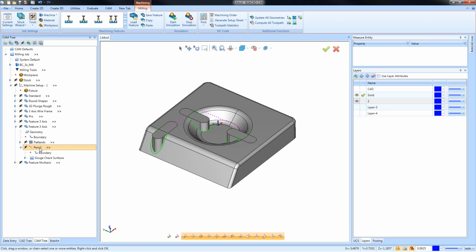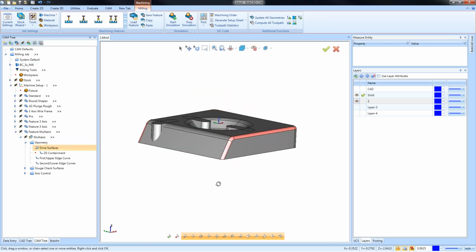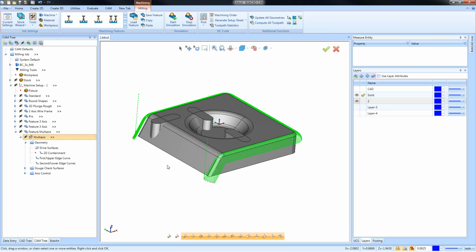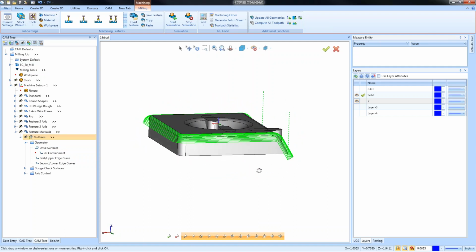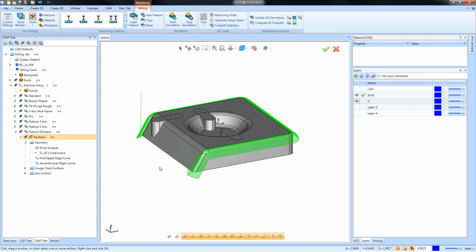And then as you elevate, if you become a Mill Premium user, I probably could do a whole webinar just on the premium toolpaths. This is an example of a morph between two curves routine. And again, this gives you a lot of control. In the multi-axis toolpaths, like Mill Premium, even though there are ways that you can make them into roughing routines, it's likely that's going to be more finishing type work. Steep and shallow specific toolpaths are in there. And I think that it's very, very useful.